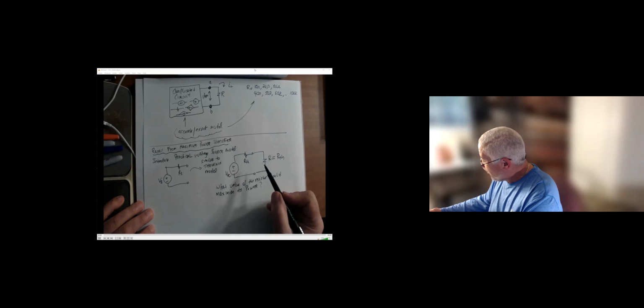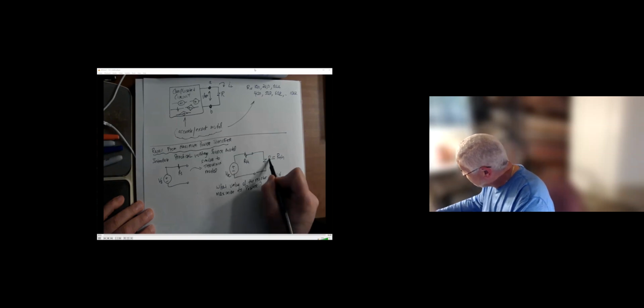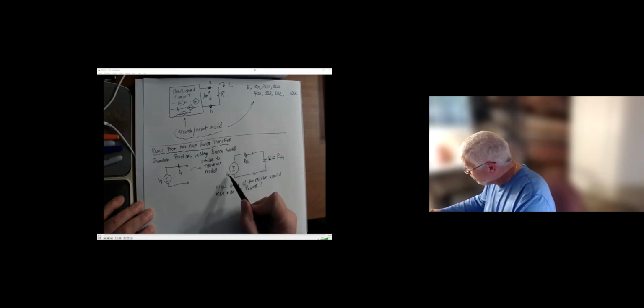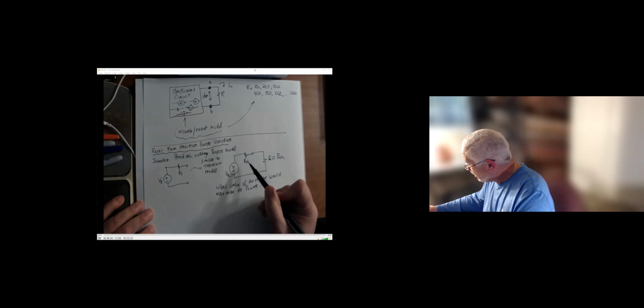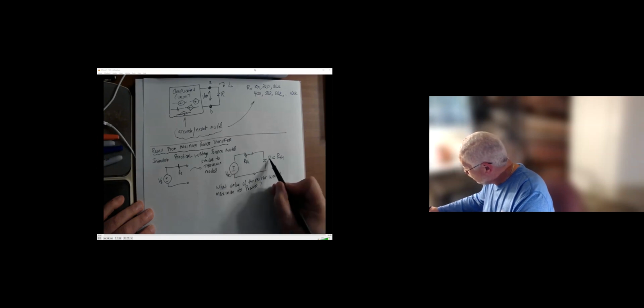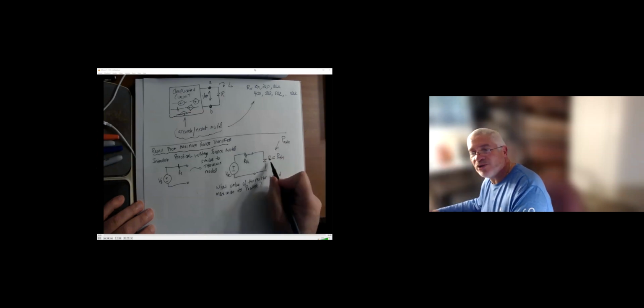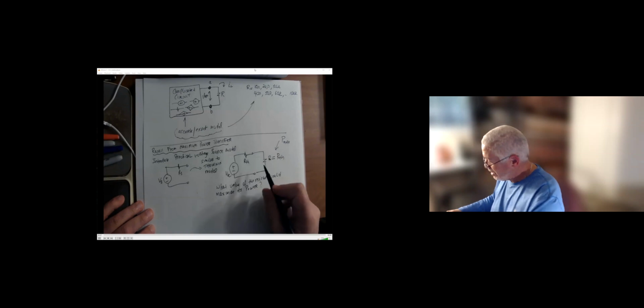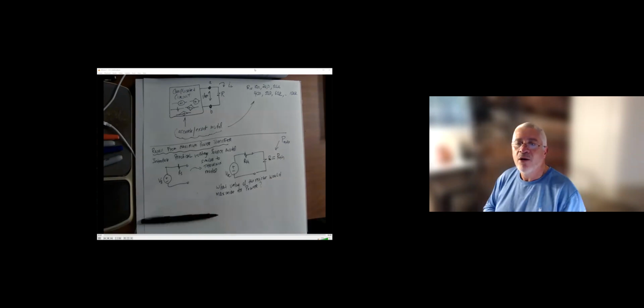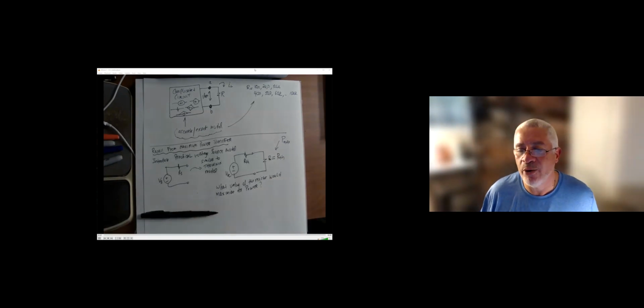So when you are asked that question, we're going to first determine the Thevenin resistance for the circuit. Then we're going to make the resistor R the Thevenin resistance and find the power, which is essentially the maximum power, having adjusted the resistor so that it is the Thevenin resistance. Just a little bit of a recap from the maximum power discussion and lecture that we have.